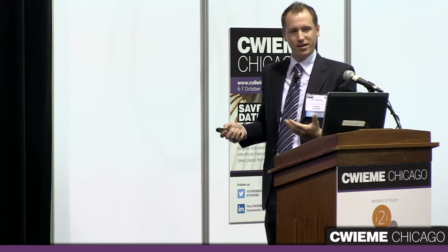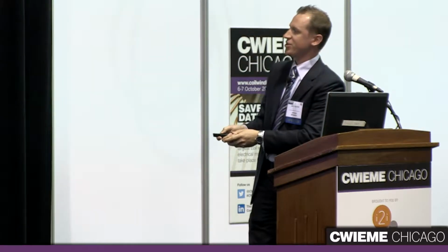How can you model that in this electric motor model? And this is one of the major messages of this talk. Well, if saturation occurs, just think of the flux linkages as a one-dimensional function of the currents. Just any sort of function, as given by this sketch here. This could be just any nonlinear function. In a real implementation, that could be a polynomial fit, or a sinusoidal fit, or a lookup table, whatever. It doesn't really matter. Important message: saturation means flux linkages become one-dimensional functions.